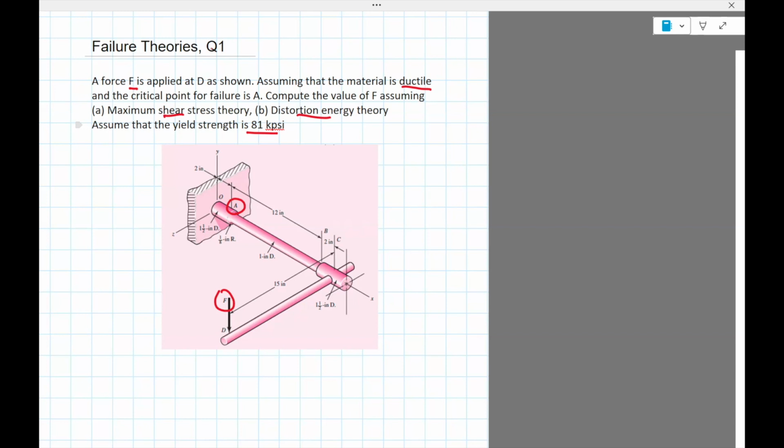It'll give you the stress for different parts, and you'll just be able to tell which part has the highest stress. And then based on that stress, maybe you'll use a factor of safety to design it. So then you can vary maybe the diameter of different parts or the length of the lever and so on, and figure out how the stress changes. That's maybe something you did in senior design.